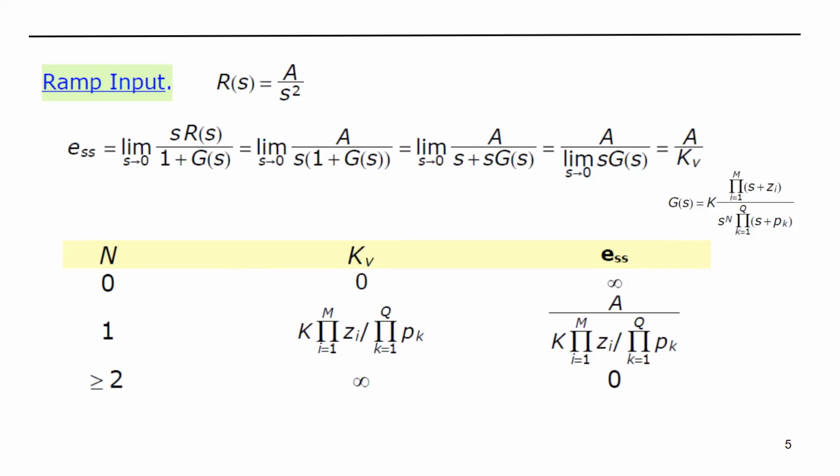So for n equal to 0, it is bad, right? The error is infinity. For this input, the steady state error will be infinity. Does that mean it will never reach steady state? Exactly, it will diverge. You want your system to go to, let's say, 1, but it doesn't reach 1. It will go to 5,000, for example. In this case, we need to enforce G of S, or alter G of S. This is what I'm saying. And now let's work an example.